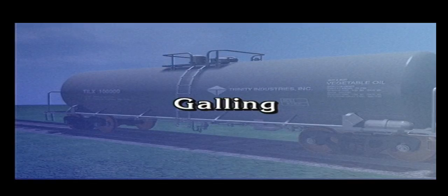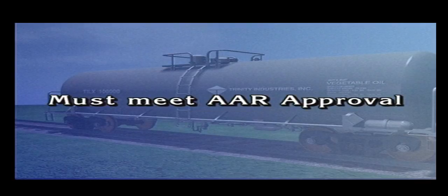Incompatibility of mating stainless steel components can be another problem. When certain materials are used for threaded connections, a condition known as galling may occur. This condition causes the materials to diffuse together in a way that prevents them from being separated. And finally, all valves and fittings, as well as their arrangement, must be AAR approved.